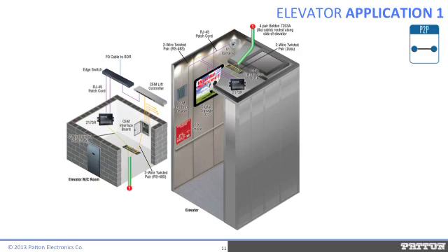So customers are turning to Patton daily. We, along with the elevator manufacturer and integrator, really are helping customers save money by avoiding the requirement to install new infrastructure. That is to say, upgrading to fiber or Cat5 plus cabling. In this application, the customer has complete control of their elevator systems via Ethernet. And to add value, they are now able to add to the install an IP camera for surveillance, IP phone for emergency calls, an elevator LCD to run various different advertising and announcements. This is all over the same single twisted pair previously running RS-485 that was used for control only.